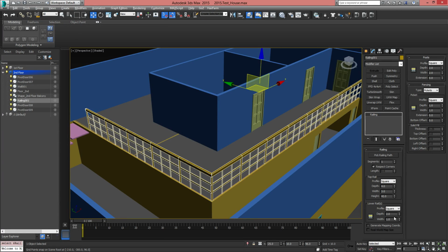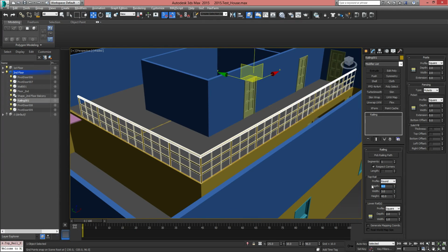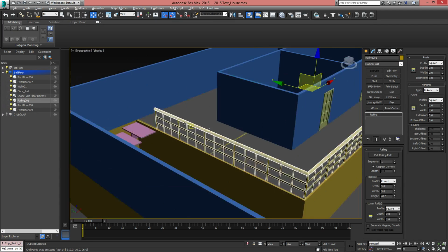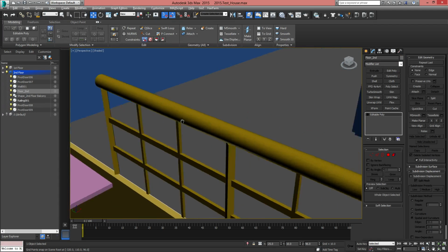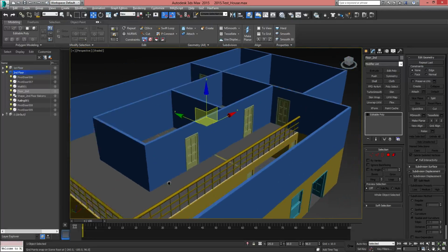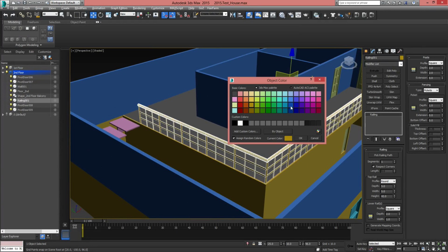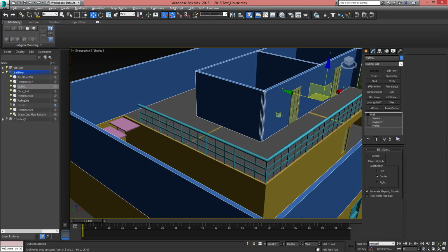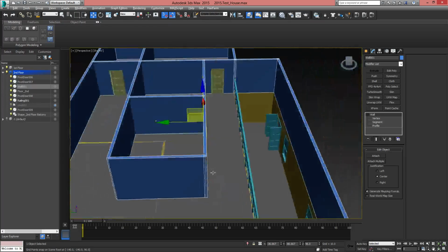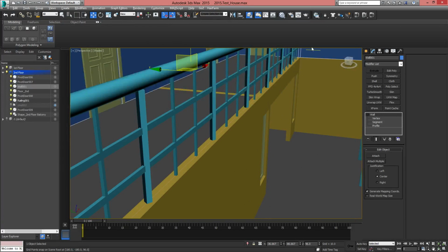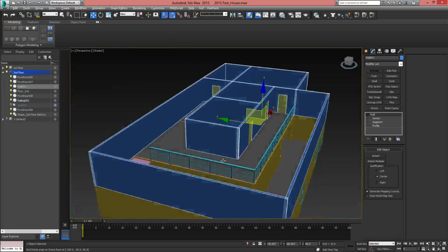Let's say for the top rail here, I don't make this rounded. Change the depth, maybe the width. Now the width and the depth need to actually match when it's rounded, so I'm going to do 5 by 5. So it makes this railing just a little bit thicker. So something like that. So now we have this railing here. I'm just going to make this a different color so it's easier to differentiate. So now I have my railing going along here. So now we don't fall.